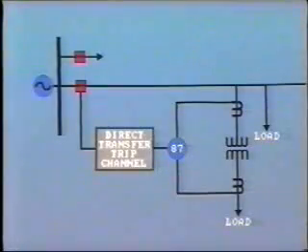The main feature of pilot protection is that it operates over distance. We have already seen that different types of communication channels and type of signal can be used between the stations. Let's now look at some typical applications. One of the most basic is the direct transfer trip. In this arrangement, operation of local protection relays, say adjacent to a transformer, will cause tripping of a breaker at some remote location. You will remember that we discussed this in an earlier tape.